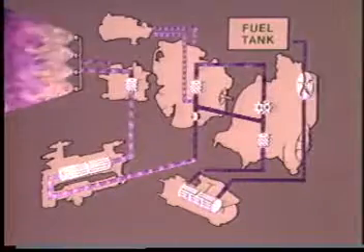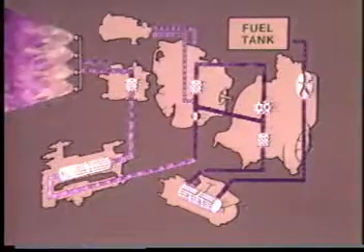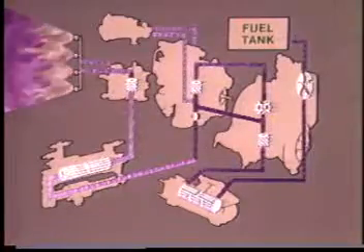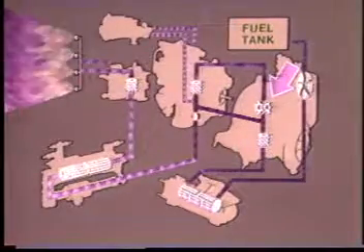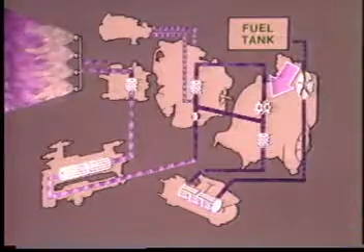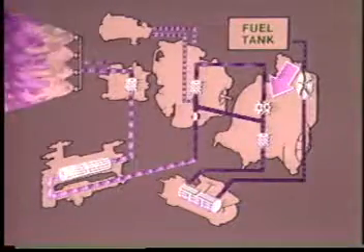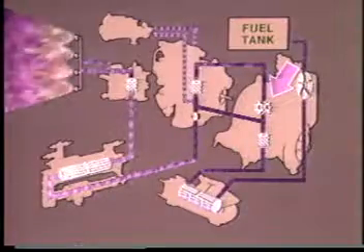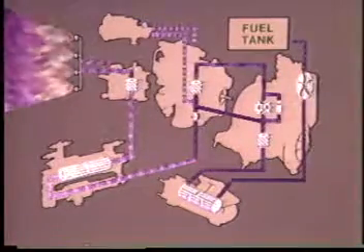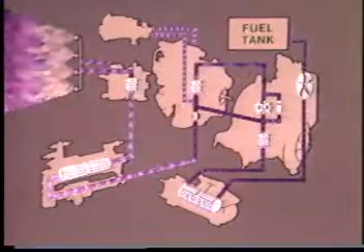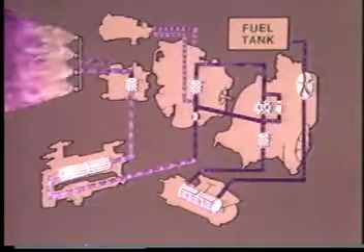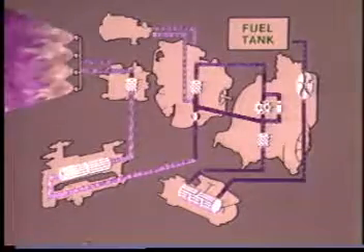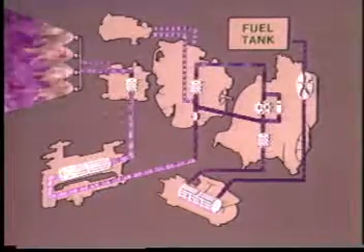Another protective measure located in the fuel pump is a high-pressure relief valve. When the pressure rise across the second stage of the fuel pump reaches 1,025 pounds per square inch, the relief valve begins to open. This prevents excess pressure from reaching the fuel control. The relief valve will be fully open when the discharge pressure rise reaches 1,040 pounds per square inch.